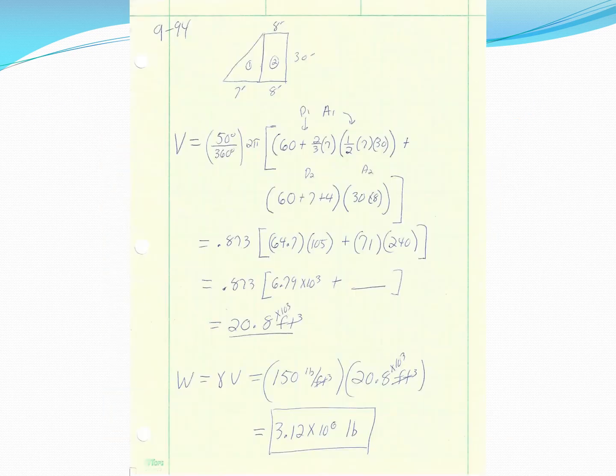You'll notice shape 1 is my triangle, shape 2 is my rectangle, and you notice how great my scale is there if you take a look at it. So remember the information that I need: I need to find the area, and I need to find the center point. These were offset by the 60 feet from the axis to the start of the shape.